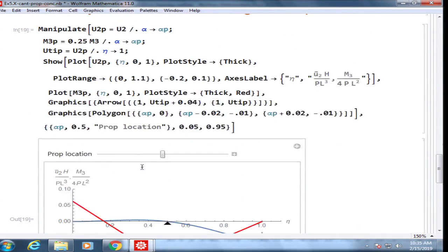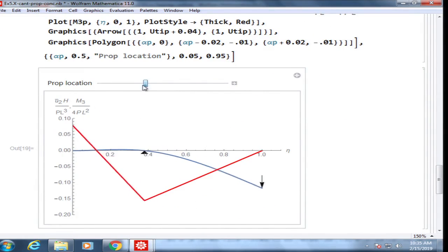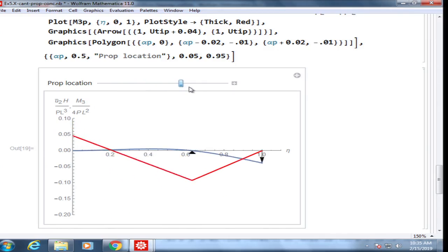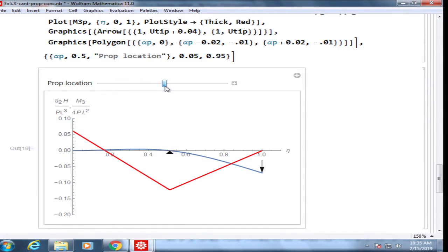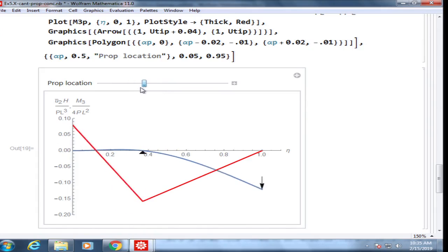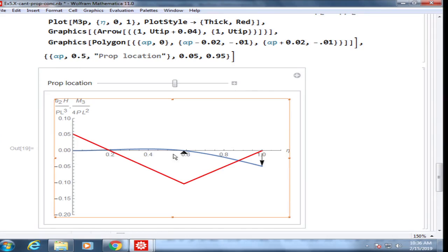And then I'm just plotting the displacement here. So if you move the support, let's say the support is in the range of 0 to 0.5, there is hardly any... so for example, if you have support here and if you have support at 0.5, the P causes some effect, but essentially your cantilever beam is being helped by putting that support.